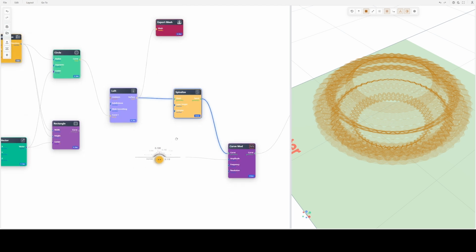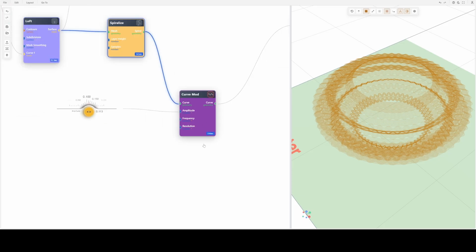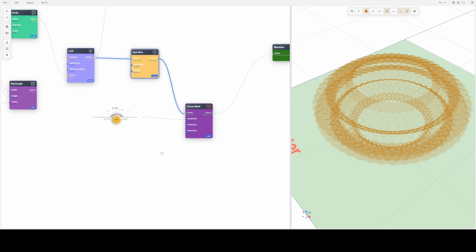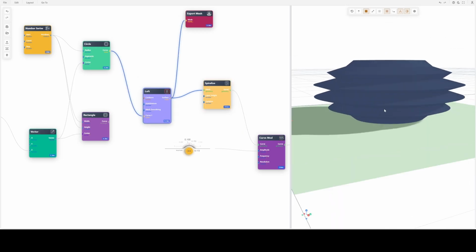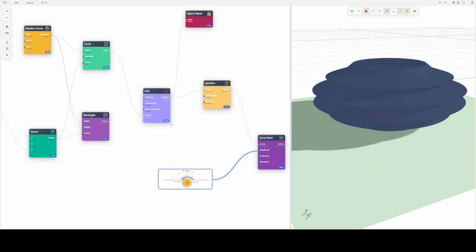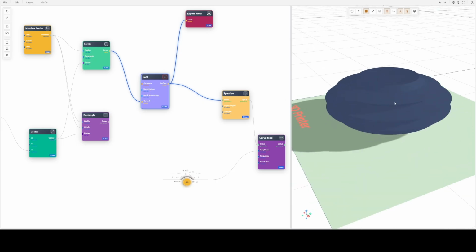So for example, if you are already here, then you have no chance. You need to change these settings and then to wait this 200 milliseconds until it's done. But let's say if you want to change your overall appearance of the base shape of the loft, then you don't need to keep these nodes connected, because they then consume time. Let's say, for example, you want to change the radius here of your circle to make your loft shape just bigger.